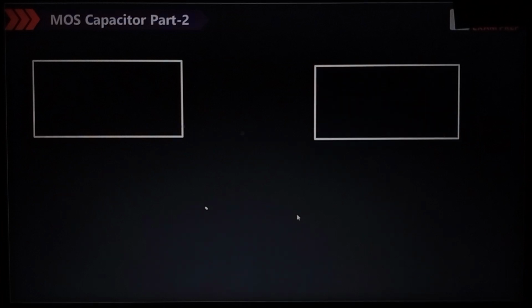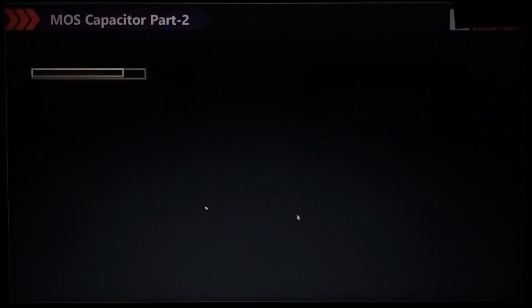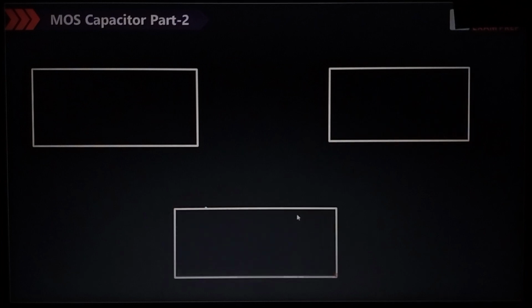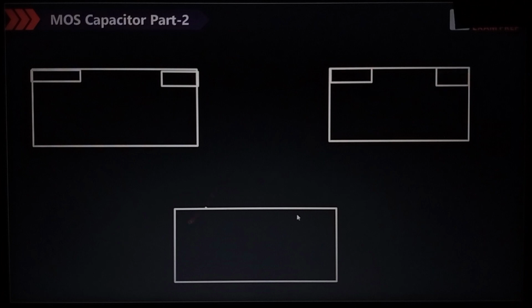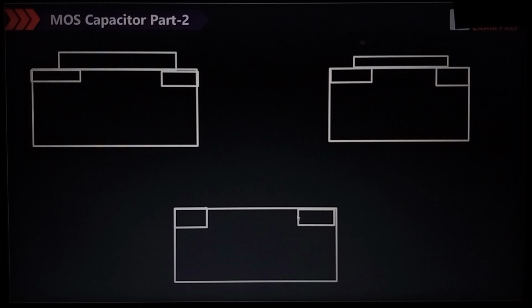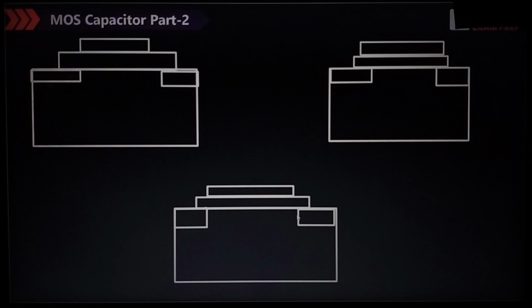Okay. So these are the 3 questions. So in the previous class, today we are going to discuss what is the accumulation and what is the depletion and what is the inversion and what is the effect on the Fermi level. Accumulation means there is an accumulation of the holes in this area. This is called channel length. This is the channel. Depletion means depletion layer increases here.